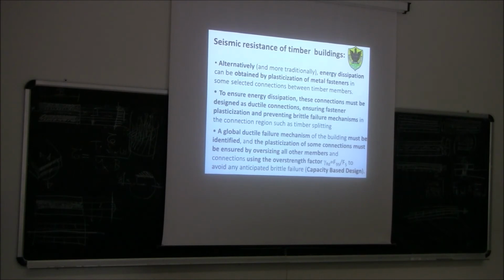Yes? Okay, perfect. So you didn't take the results of the analysis. Why didn't you take the results of the analysis? Because we had to guarantee that the failure for shear would occur after the one for bending. Why is that? Because shear is a brittle failure mechanism.